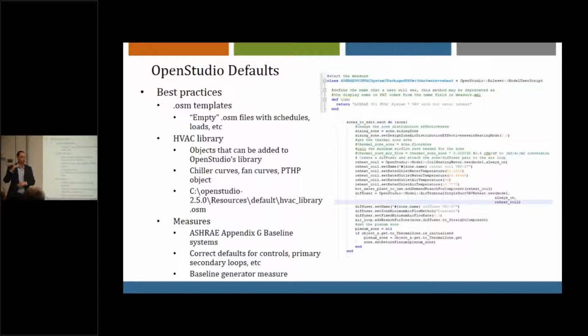All the chillers that the EnergyPlus library has, so I can have a bunch of chillers I can grab and try and get the right IPLV from. So that's definitely a huge recommendation. It saved us a bunch of time to go in there and hack into that and add your own stuff, and then it's always available when you're in the OS app. Sometimes your computer doesn't want you to, and you have to move it and save it and then move it back, but